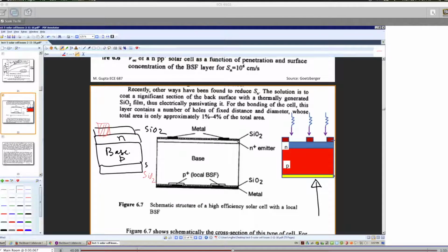But if you just put a metal on this N semiconductor, we just learned that that's not a good interface. That gives you higher recombination. So what we need to do? That's right. So what is done is we put a N plus layer here. Okay.